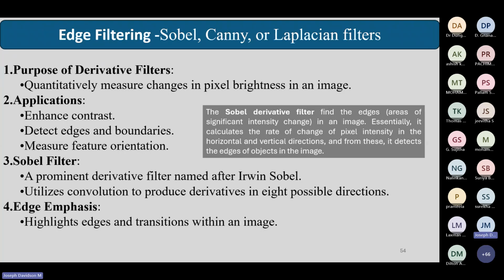So it calculates the rate of change of pixel intensity from an inner region to a boundary region, and whenever there is a significant variation, it concludes that there is an edge, and that edge should not be destroyed. If I destroy it, then two grains will merge. I cannot count the numbers, and I cannot come to any meaningful conclusion, correct?